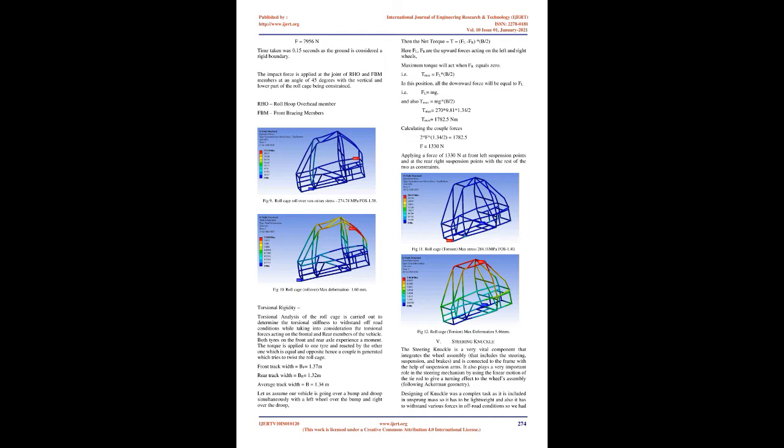We also did the mesh dependency test, grid independence, for different element sizes and found the saturation around 3 mm, as shown in the figure. We have used the appropriate value of proximity for the joints, as they are the areas of high stress concentration. The boundary conditions were considered such that they satisfy the actual dynamic loading conditions in static structural.